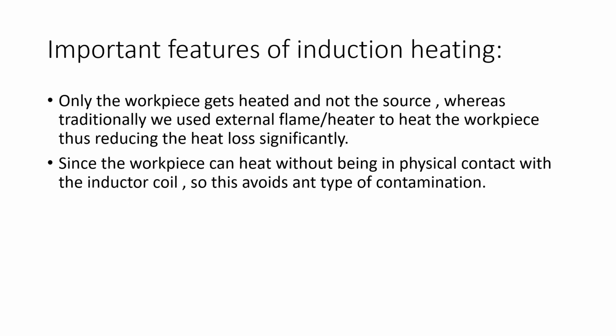Here are some important features of induction heating devices. Only the workpiece gets heated and not the source, because eddy currents are produced only in the workpiece. Whereas traditionally we used an external flame or heater to heat the workpiece, we have now reduced the heat loss significantly while using the induction cooktop. Since the workpiece can heat without being in physical contact with the inductor coil, this avoids any type of contamination.